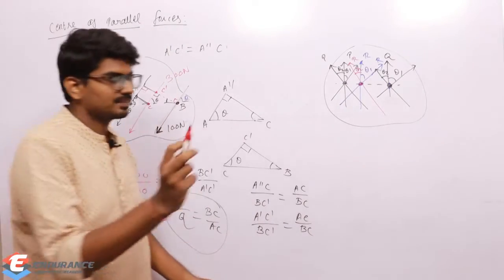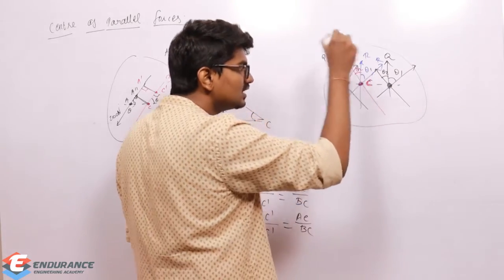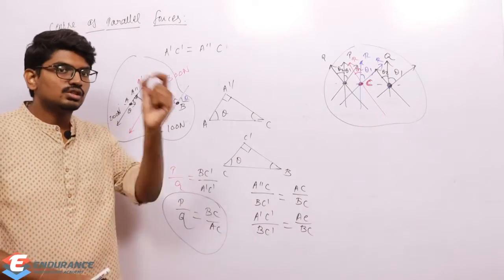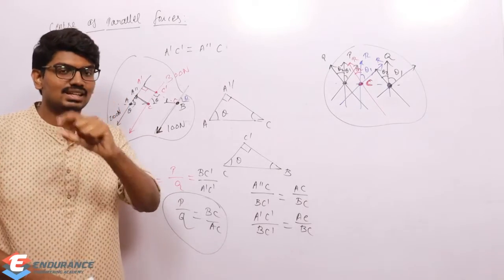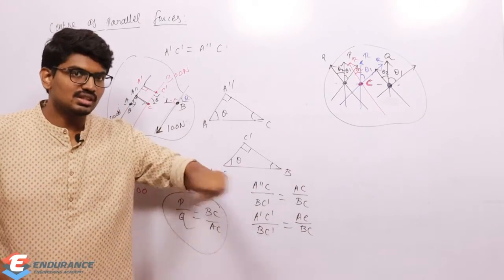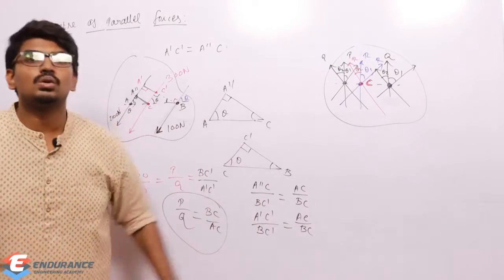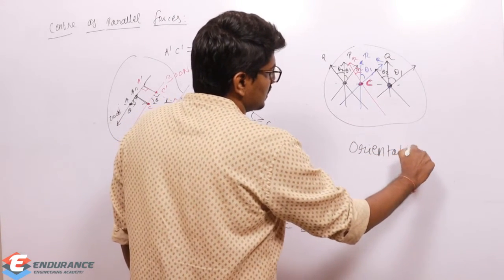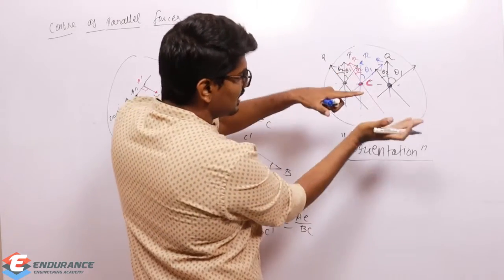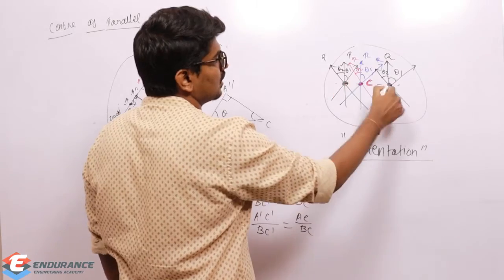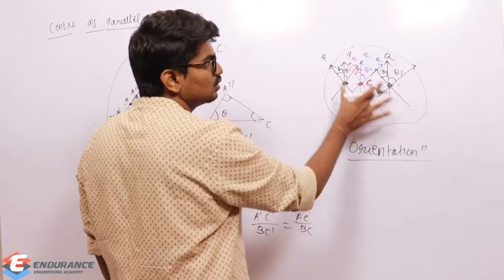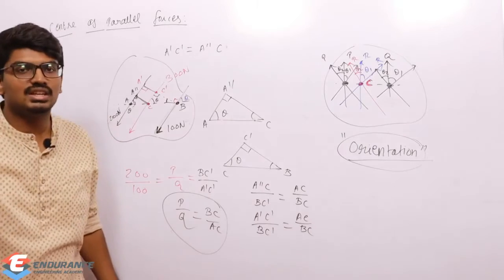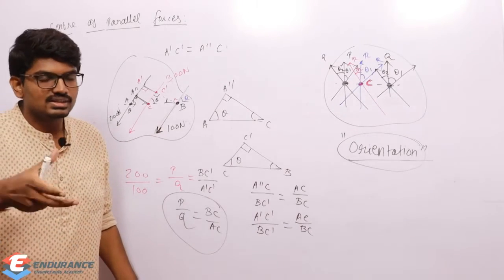So that point through which the resultant of the parallel forces, here I'm just taking 2 parallel forces, but you can take n number of parallel forces, it is that point through which the resultant always passes, irrespective of the orientation of the forces. Whatever may be the orientation, let the two forces be vertical, or inclined in this direction or in this direction, until or unless you are changing this point through which the two forces are passing, you are only changing the orientation, then my resultant won't change the point through which it is passing, only its orientation will change.